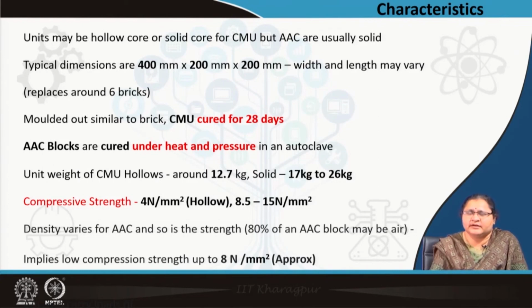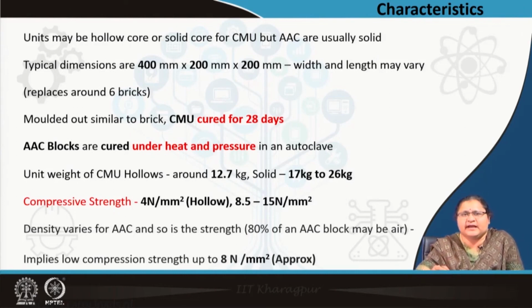Inside, autoclaved aerated blocks are very smooth, as we had seen in the picture. So, what is happening is you can avoid the plaster component, there is a saving, and because it has air inside it, it is acting as a good insulator.